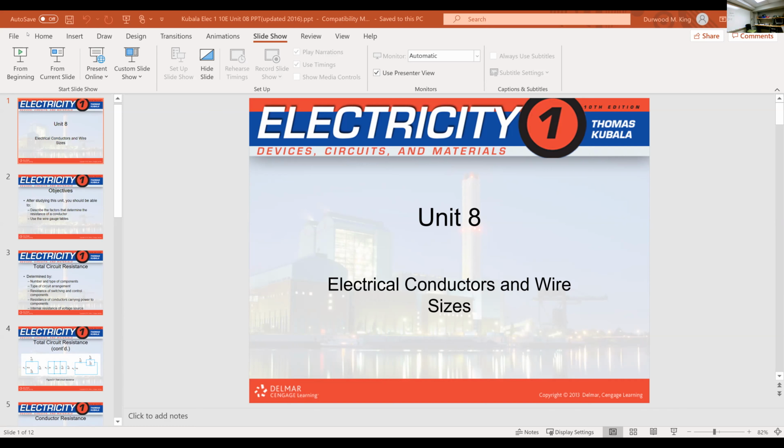Here, 3 of them in series, you have a total of 18 ohms. Y'all agree with that? Because it's series. Here, you take those same 6 ohm resistors and put them in parallel, and you end up with 2. The simple way to figure that would be resistance of one of them divided by however many of them there are, and there's 3 of them. So 6 ohms divided by 3 would give you 2.